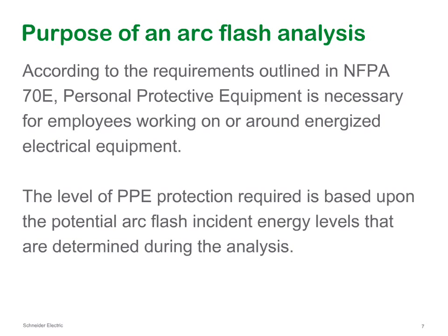For example, the task of troubleshooting on a piece of equipment typically cannot be performed if we shut down the equipment. So if the equipment is energized and the worker is performing troubleshooting tasks on it as it should be done, then in that case, that worker is subjected to that arc flash energy, and the task cannot be performed with the equipment shut down. So in that case, we have to put the right PPE on that worker, and that is basically what we are talking about here. The output of this arc flash analysis would be an engineering calculation that would provide us with those energy levels that the worker will have to protect himself against.